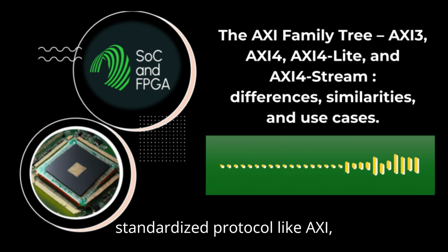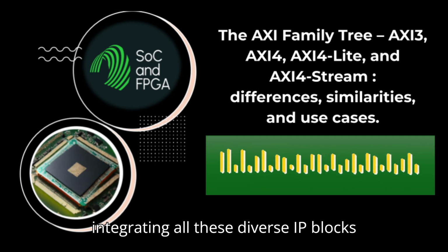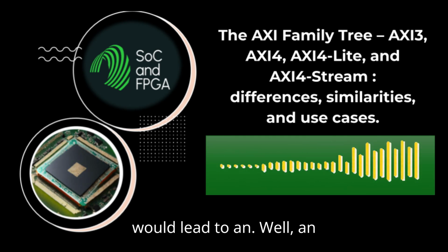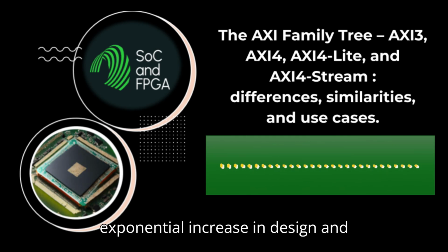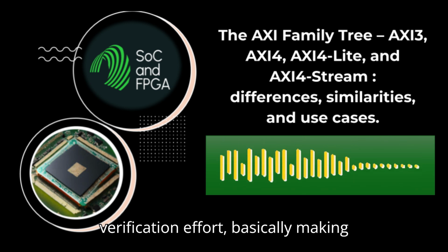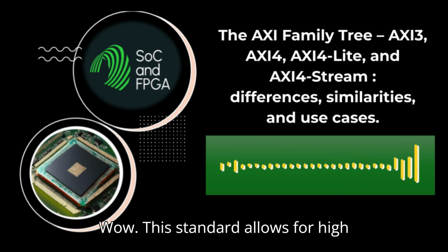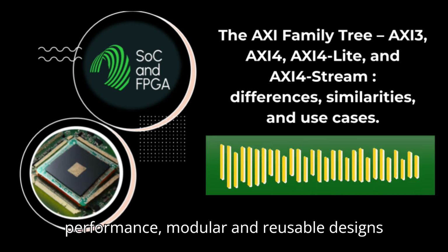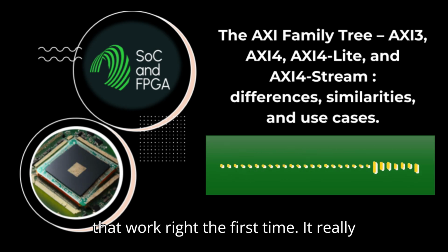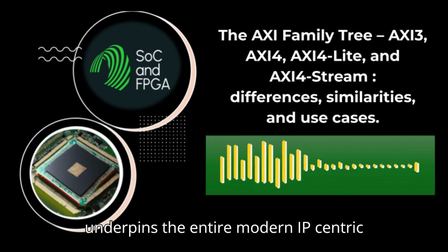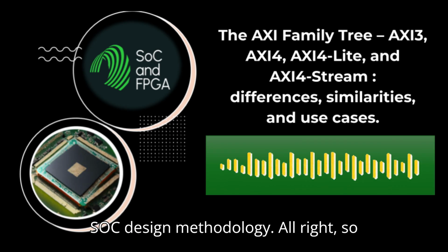Without a standardized protocol like AXI, integrating all these diverse IP blocks would lead to an exponential increase in design and verification effort, basically making large-scale SoC development impractical. Wow. This standard allows for high-performance, modular, and reusable designs that work right the first time. It really underpins the entire modern IP-centric SoC design methodology.